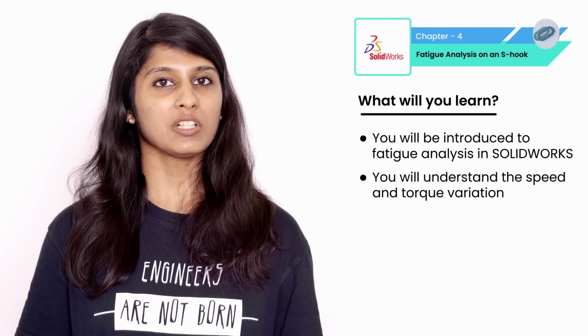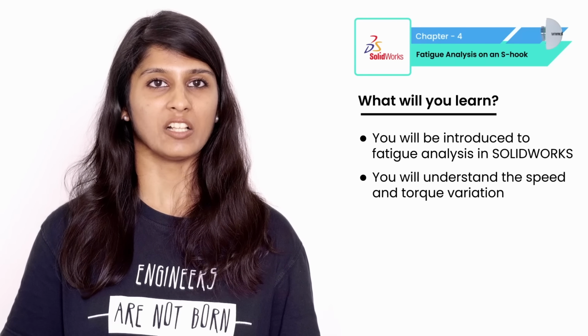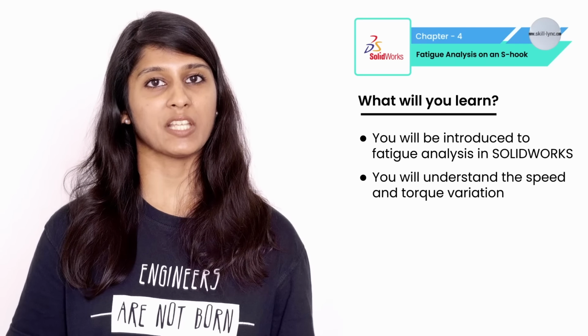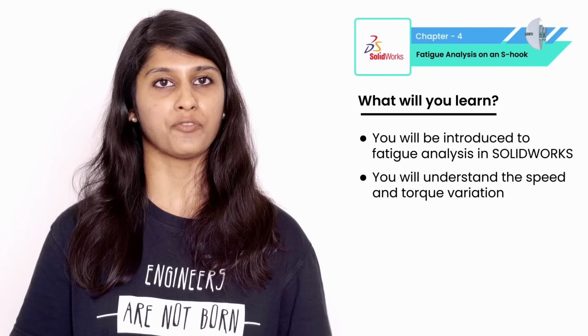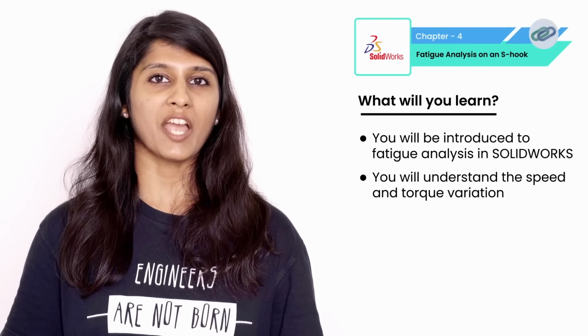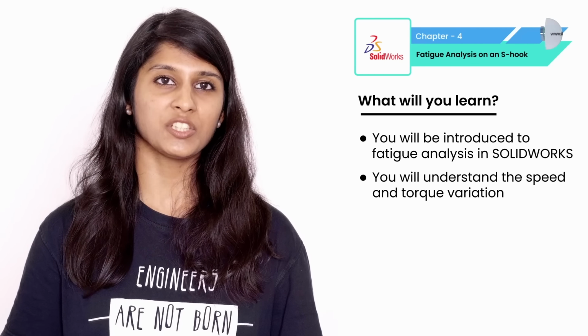In the fourth chapter, we'll delve into fatigue analysis with an S-hook. You'll explore how to utilize the SN curve for fatigue analysis, apply different loading types, and import results from static analysis to fatigue analysis. We'll also guide you through creating animations from the analysis results.